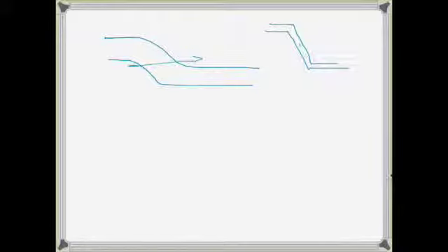And so the algorithm that we developed, and all this sort of thing is just something you figure out by trial and error, is that everywhere locally you define the middle of the band gap. You're keeping track of the potential, so your valence band edge, your conduction band edge, and you take the halfway point, and that's your middle of the band gap. We can call that E sub I, like you do in your semiconductor books. They call that the intrinsic level. It's not exactly the intrinsic level. We'll just call it that. It's the middle of the gap.